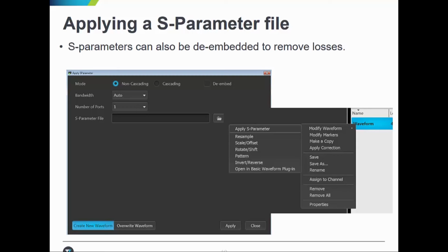Other instances, you may want to de-embed those particular devices out of the losses that are associated with the network. So this capability gives you the ability to either de-embed it or not de-embed it and use it as a simulation of what that particular device will do to the network of the system. This S parameter provides the magnitude and phase response of a set of frequency values of different combinations of the input-output of the device. The S parameter, each combination of the input-output defines different characteristics of the device.